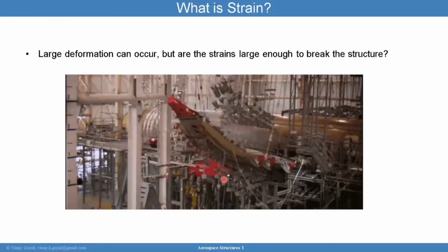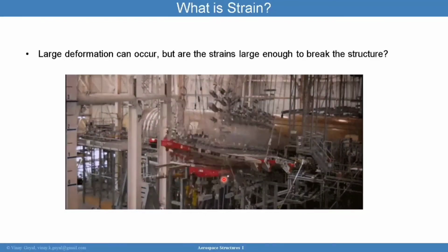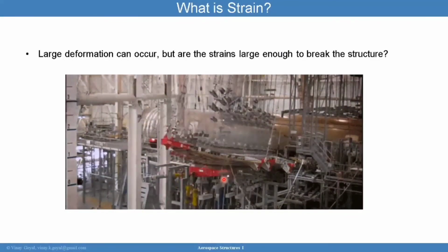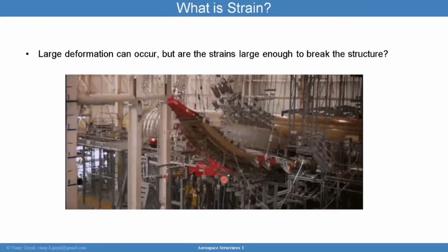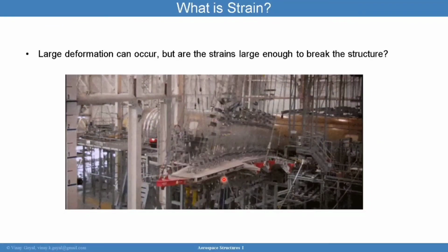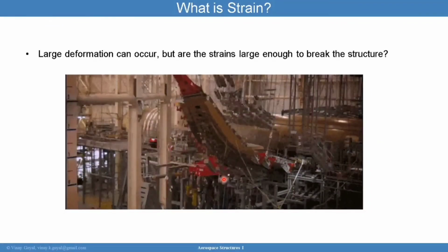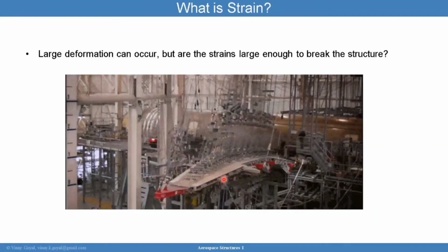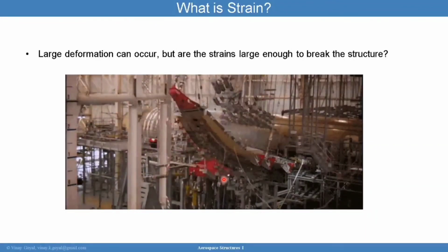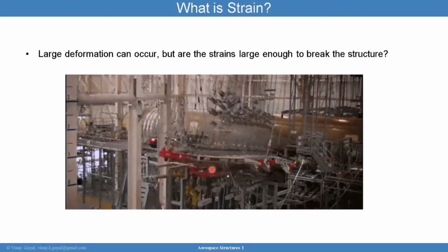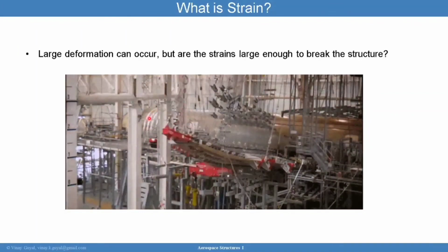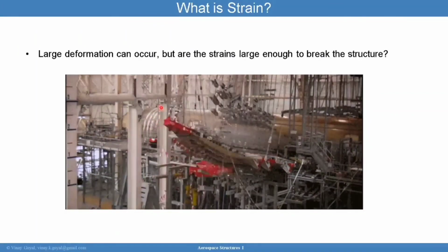And this wing is going to deform 20 to 35 feet or more. But the idea here is to demonstrate that the wing can take the loading conditions in flight. As you can see here, the load cells are attached to the wing. You can see the wingtip deforms or deflects a lot.